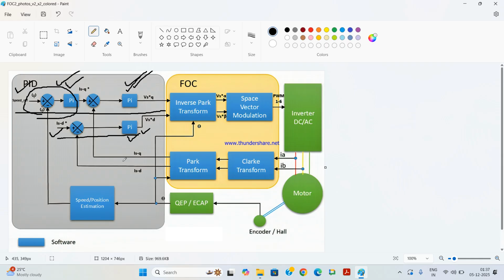So for medium voltage drive, once tuning is concerned, you have to know the control loops inside the control system. You have to find out the input and output of each loop. Then you have to take a no load run for the motor and capture those parameters, with the sampling time at most equal to the switching frequency of the inverter.